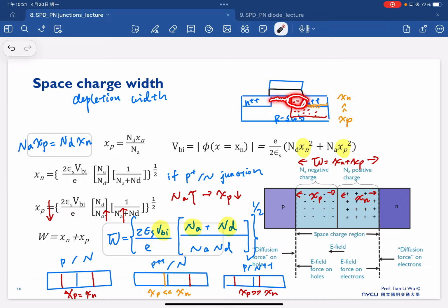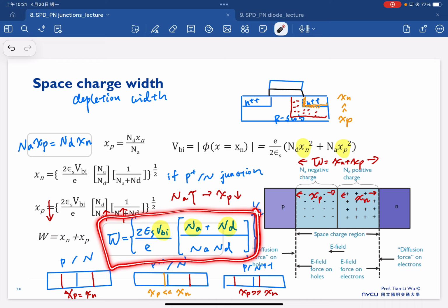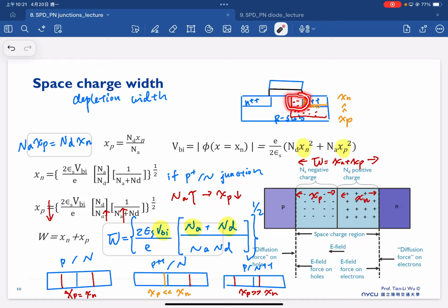We will explain this in detail later. When we talk about MOSFETs, we will definitely need to use this depletion region again to understand the device operation. This is just an idea of why this equation is sometimes more important than just estimating depletion width in the PN junction, because in reality, a PN junction is not going to be a device by itself. Inside a real device, there are lots of parasitic PN junctions. So this is one idea of how this part can certainly influence our channel and our transistor operations.